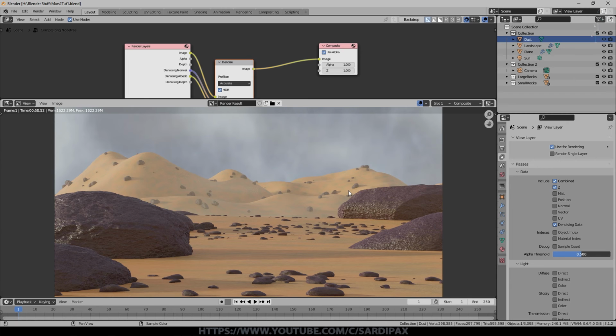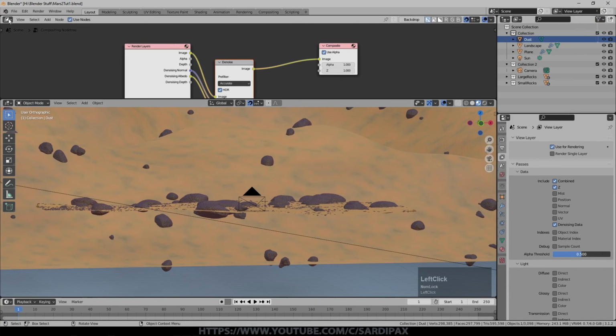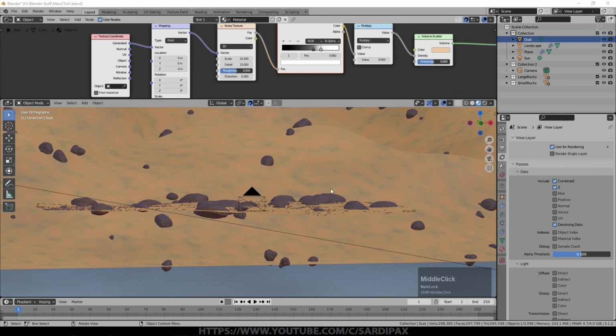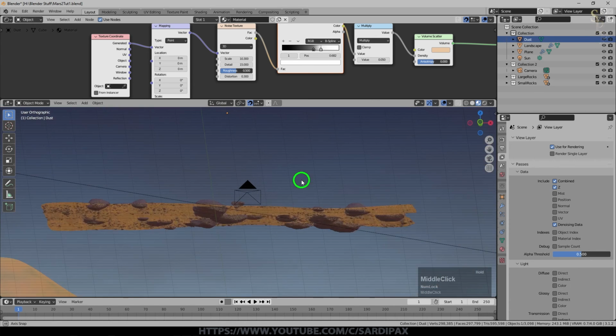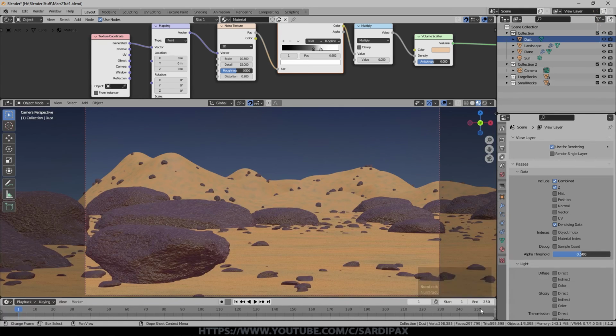So having done that, how do you animate your volumetrics? Well, in essence, it's pretty straightforward. We go back to the shader editor and we've already put the nodes in that we need. But what I found was you can't really assess whether the wind, as it were, is moving at an appropriate speed with the viewport and looking at still images. You really need to see an animation. So what I ended up doing, I ultimately made an animation of about 500 frames, but to just test out how things were working on the animated volumetrics, I limited the start and end frame to about 100 frames and then just rendered the animation and had a look to see how that looked.